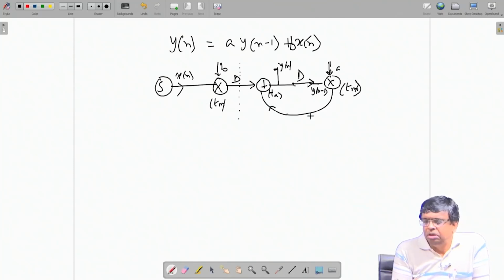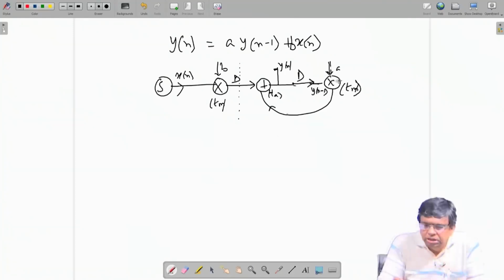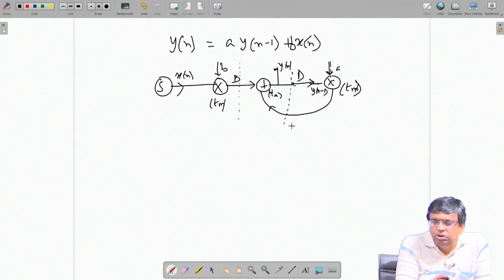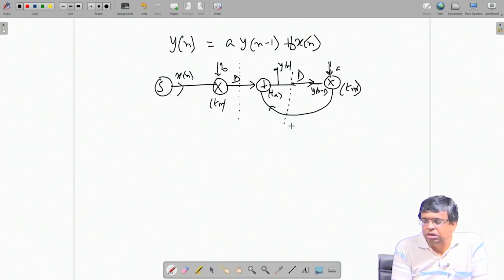Each node is also an edge. Each node is also a path actually, the shortest possible path. So, T m plus T a. I want to bring a delay here. So, if I do cut set retiming, this side is one sector. If you take out these two edges, this side is one sector and this single node is another sector. From left to right, I have a delay. From right to left, no delay. So, you can take it out and bring the delay here.